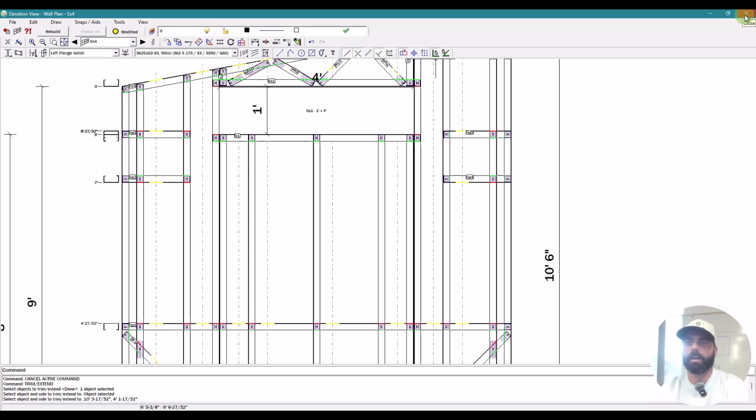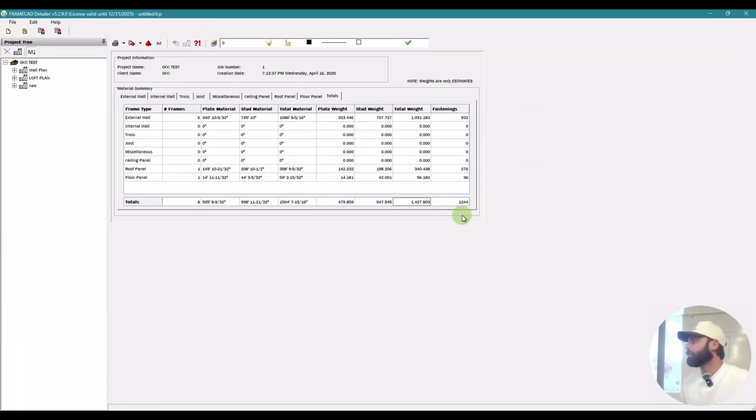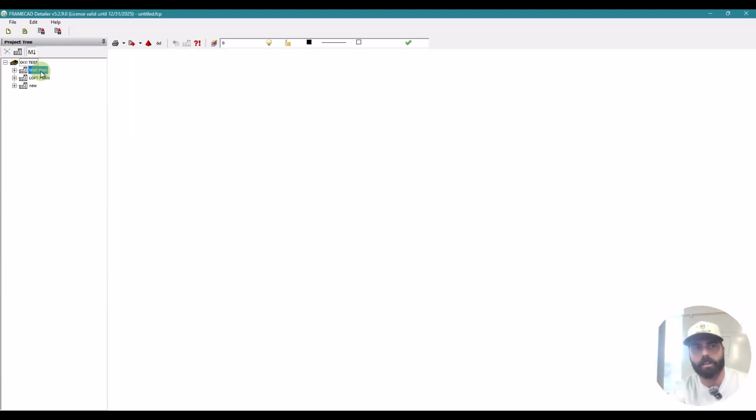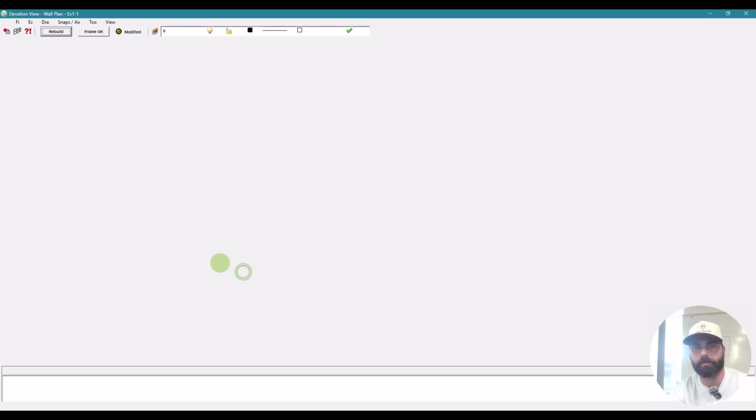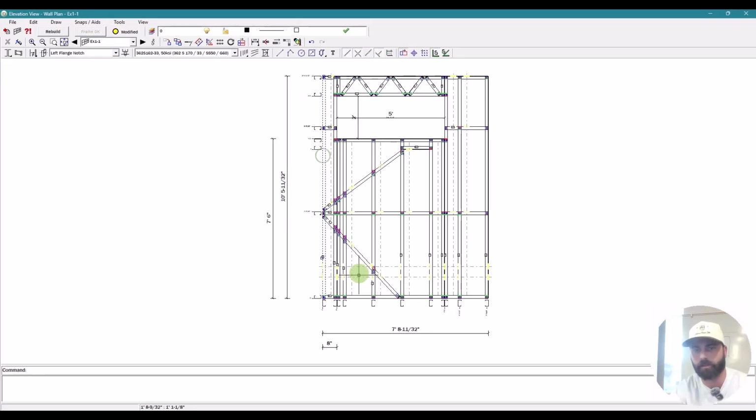Following these studs we had all of these little webs coming out, and then some braces with a lot of webbing getting removed, especially if you're doing an 8-foot truss or a header. We'll slow the machine down because as you're removing webbing material, you have an increased chance of slip or crinkling off of all of those web cuts and web notches. So we'll typically run anything from 5%, the slowest setting on the machine, to about 85, 90% if we're printing.